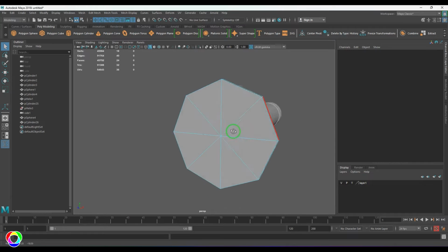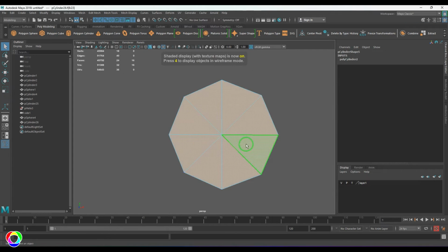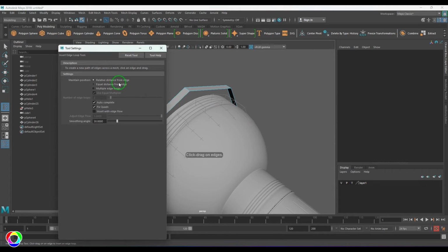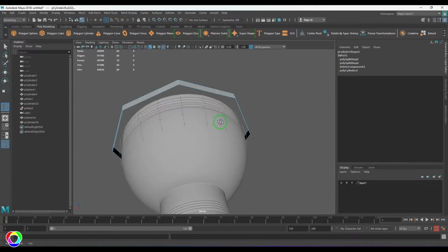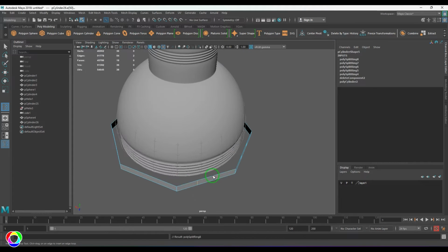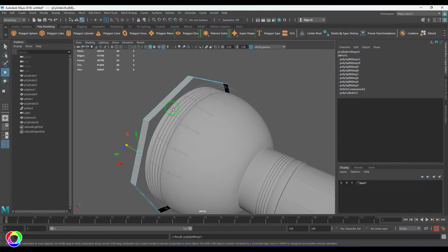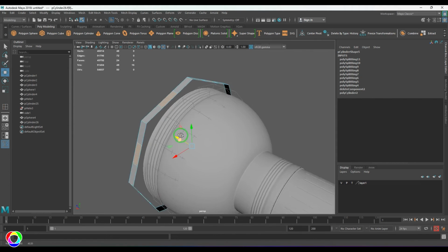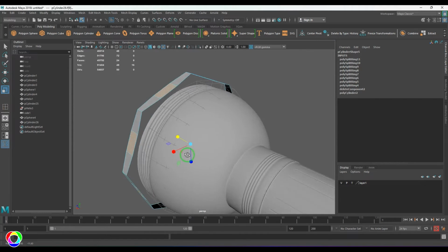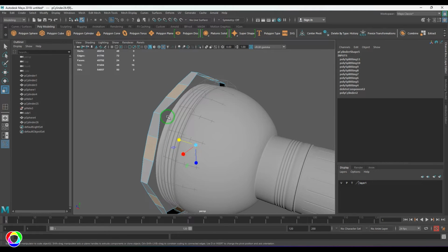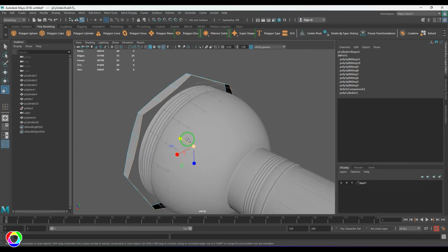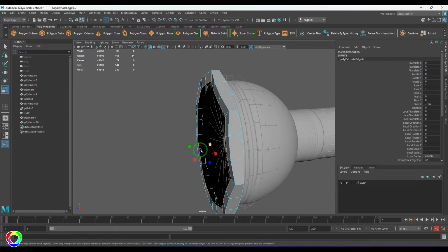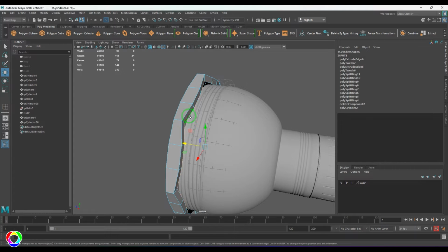Okay, now I'll be selecting those faces. Okay, and I'll be adding loops. I'll take the insert edge loop tool, multiple edges too, and then start adding lines on all sides there. Okay, now I'm going to select those faces like that, and I'm going to scale it, and this gives that nice shape here. Okay, now let me select this one and extrude it and extrude it.